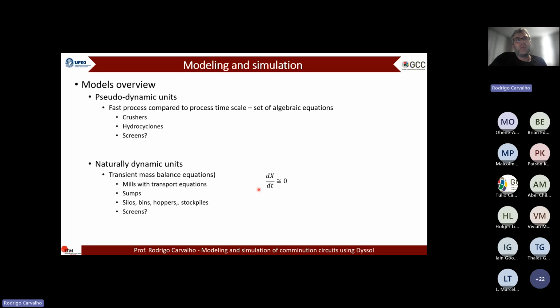Sometimes there's a risk that when you jump from one state to the other, you miss some bottlenecks, like an overshoot. The mill may become clogged or overfilled for a certain period of time that you wouldn't see when doing a steady state simulation. So this transition between steady states may show you some bottlenecks that you can only see or predict using dynamic simulators or simulations.